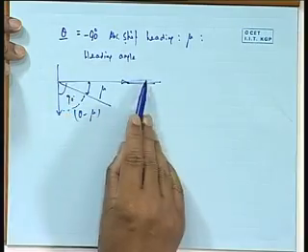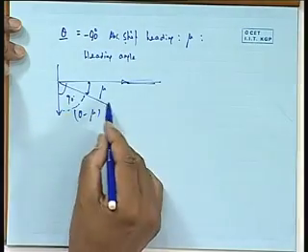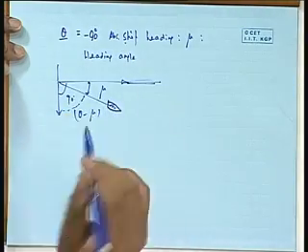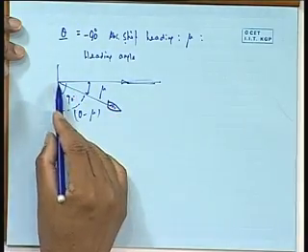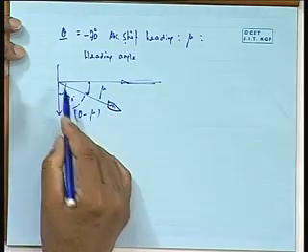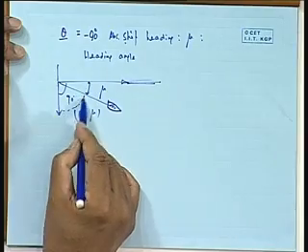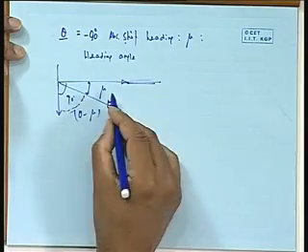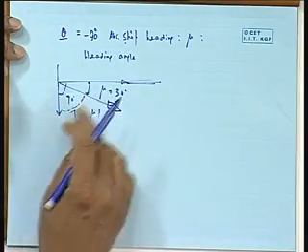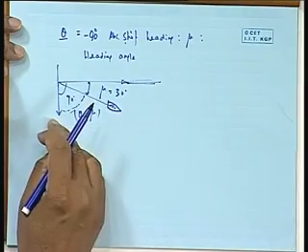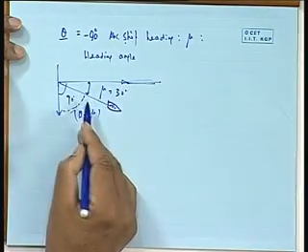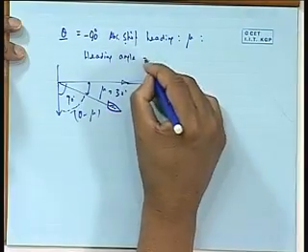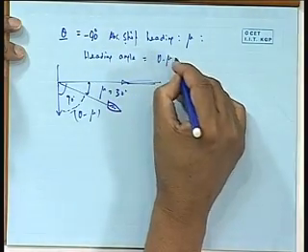So wave is coming from this direction, but the ship is moving in this direction. Now I take all the waves from this direction. All these waves are making an angle of theta minus mu. Say this is equal to 30 degree. So that means I am trying to find out the response when the ship is moving in all these waves at a heading of 60 degree. So now theta minus mu equals 60 degree.